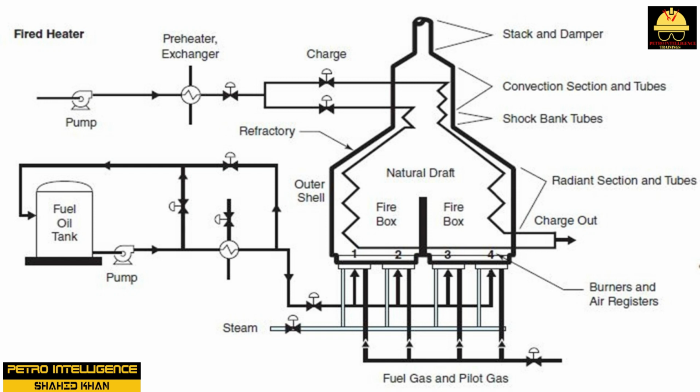Excess oxygen in the furnace is carefully controlled as it enters the base of the furnace. This control takes place as the fuel and primary air mix at the burner and is enhanced by adjustments on the secondary air registers mounted on the outside of the burner. An oxygen monitor carefully tracks the composition of the hot combustion gases.